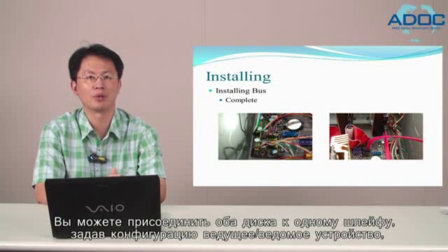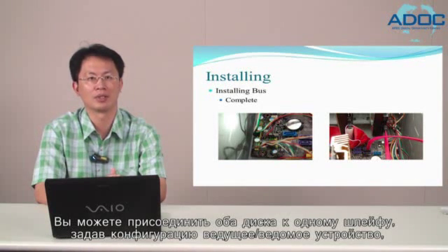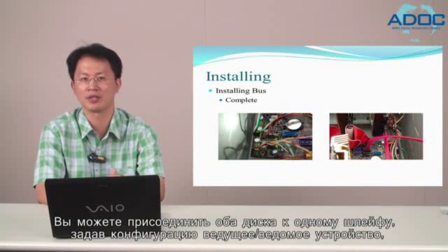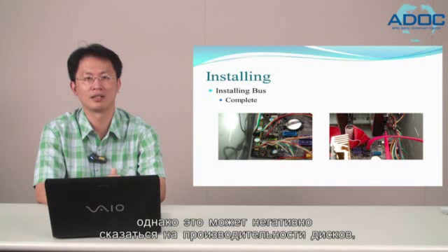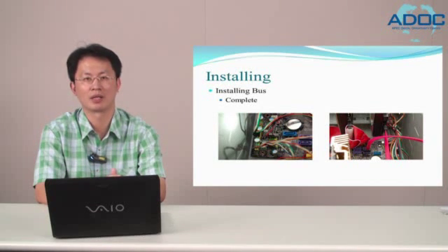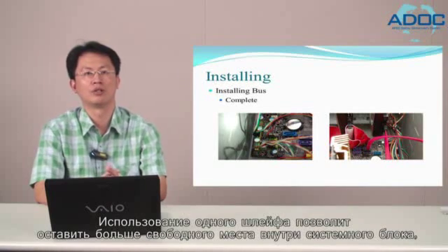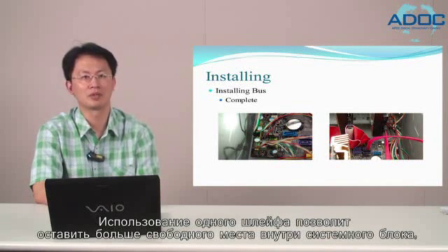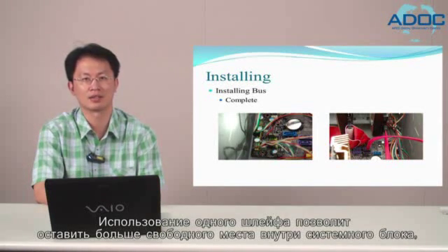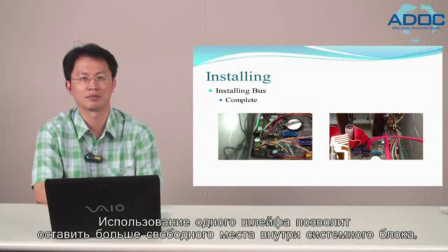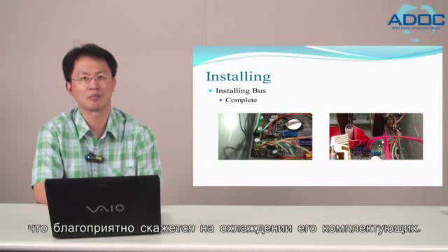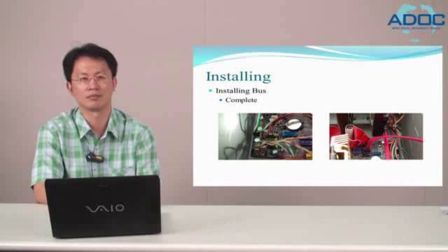You could attach both drives to 1 cable in a master slave configuration, but this can hurt the drive's performance. So we recommend using 2 separate cables. However, using just 1 cable does mean less clutter inside your case, which can keep components cooler.